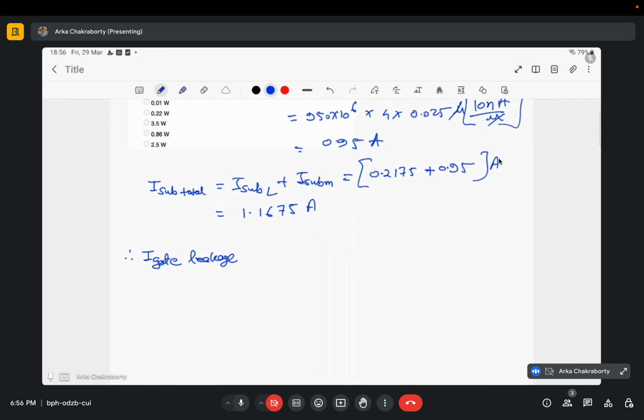Logic of course consists of PMOS and NMOS, and memory devices also, if made up of some kind of SRAM cell, then both PMOS and NMOS are involved. If DRAMs or flash memories are used, they are basically NMOS devices only. But here I will not be considering whether my memory devices are PMOS or NMOS. I will be considering gate leakage due to all the transistors.